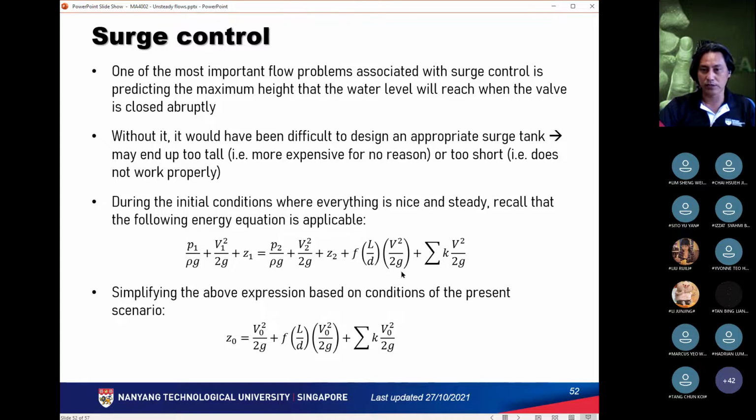Basically, this is an energy statement that says the total sum of three flow energy components, which is the static pressure head, the kinematic pressure head, and the gravitational pressure head, at somewhere far, let's say at the reservoir, must be the same as the sum of the same three energy terms taken at another location, plus whatever frictional losses you encounter along the pipeline, plus whatever minor losses, and so on. And of course, if your pipeline has a pump somewhere, I'm quite sure you know where to put the pump pressure here.